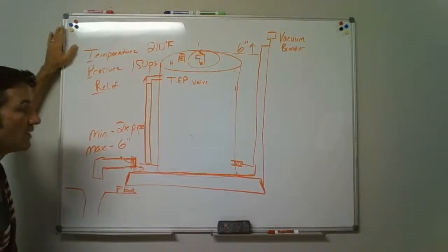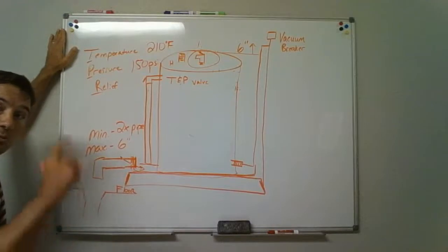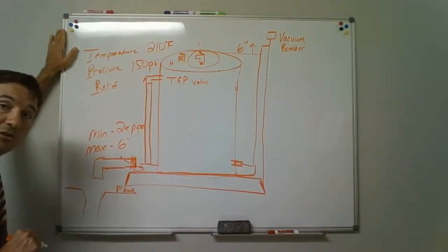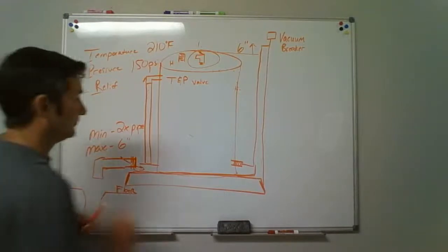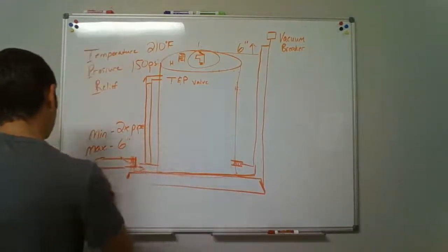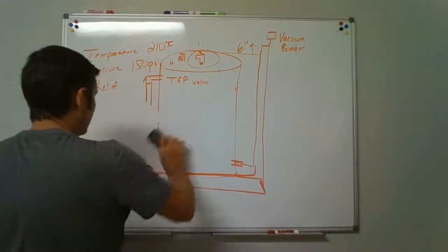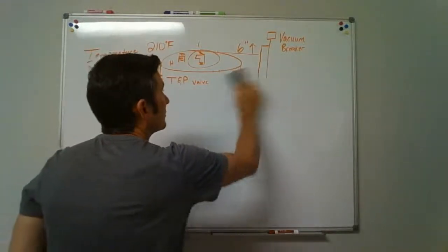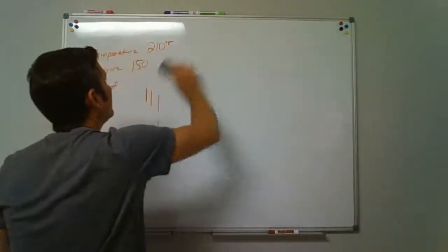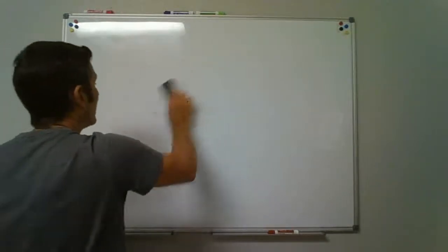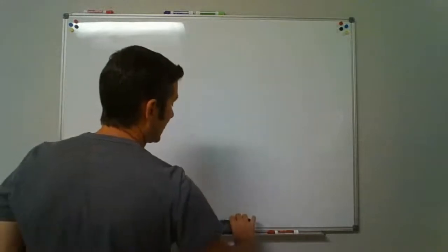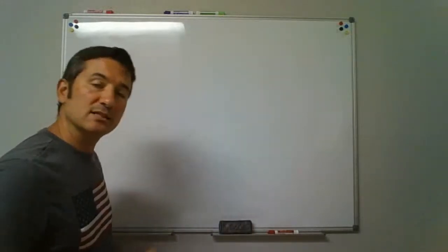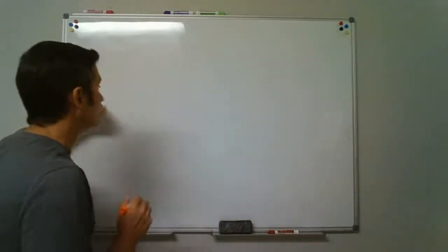Maybe you've got this. It might be suspended. Let's just say the little water heater is suspended over a janitor's closet area. Let me erase some of this and make a little different picture. It says you could also put it to a waste receptor. The one thing we can't do is just plumb it in and tie it in directly. It's got to tie in indirectly.